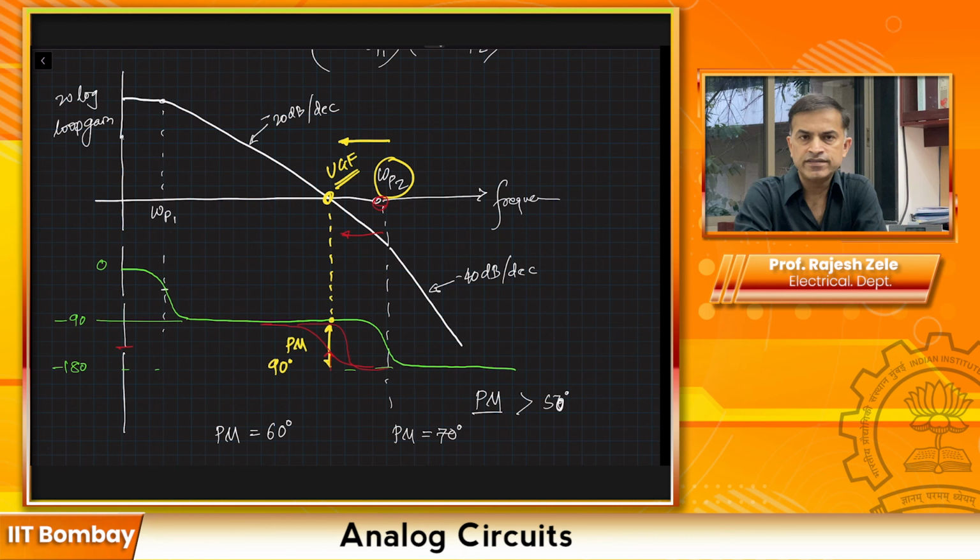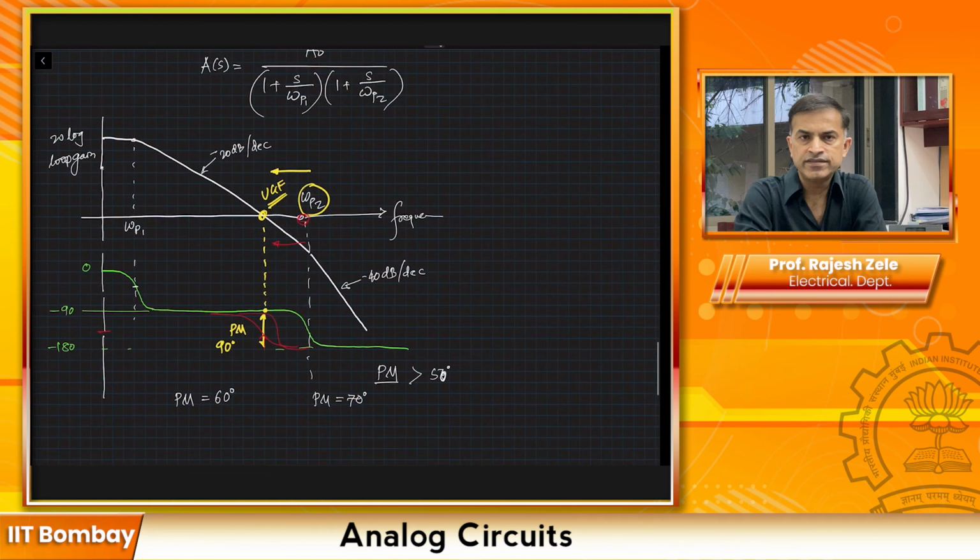So why am I telling you all these things? Okay, if you remember, when we were doing op amps, when we just did a simple one stage op amp, which is a gm Rout type of amplifier, we get some gain and we get just one output pole, which would be the single pole amplifier, and it's unconditionally stable. Now, to get more and more gain, we like to put more gm Rout stages in cascade so that we can get more gain.